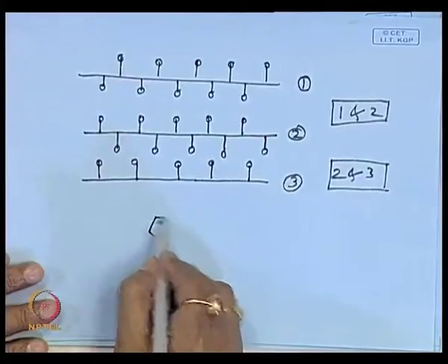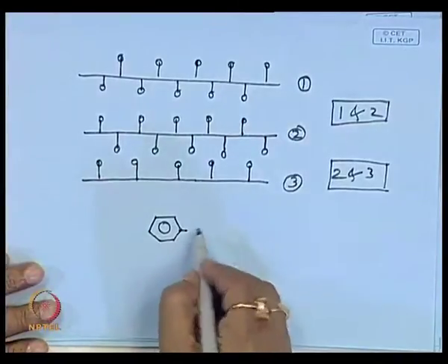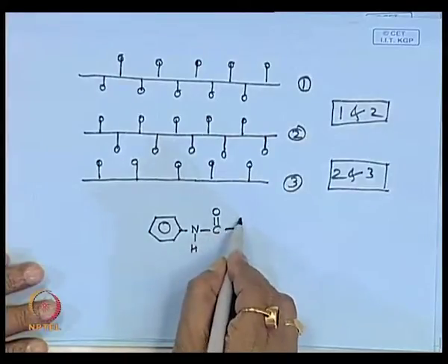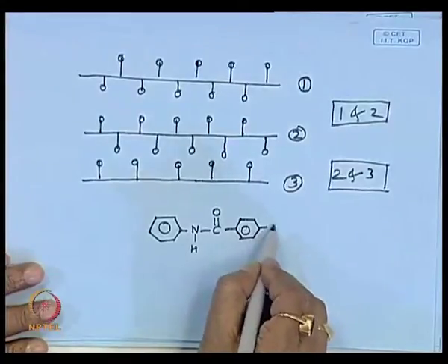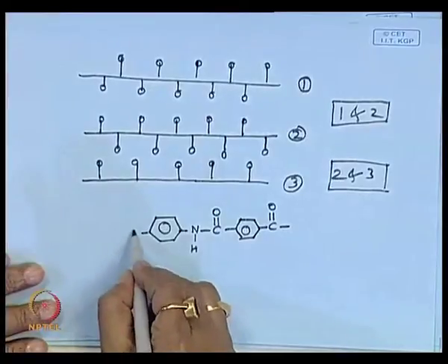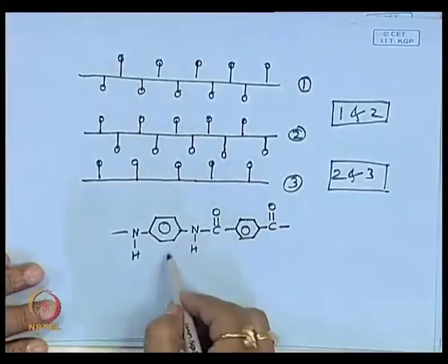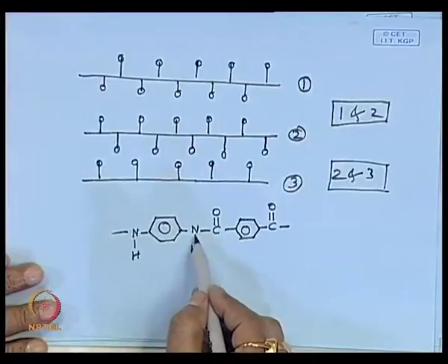Where does it come from? Now, this Kevlar fiber, I think you remember the formula of this Kevlar, aromatic polyamide. So, it is made from terephthalic acid and phenylenediamine, all right. Am I right? So, here you see, the hydrogen is connected to nitrogen.